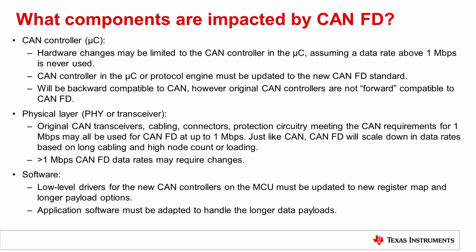Software. Low-level drivers for the new CAN controllers on the MCU must be updated to new register map and longer payload options. Application software must be adapted to handle the longer data payloads.